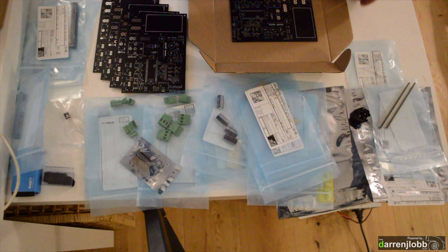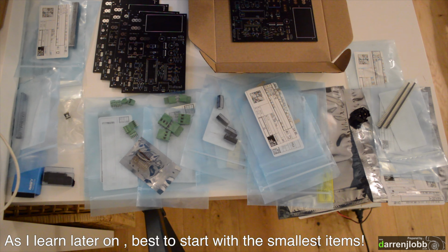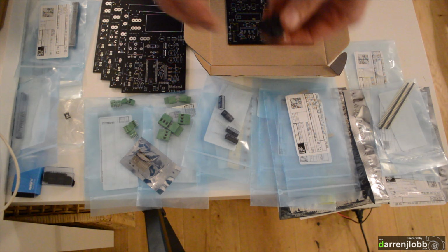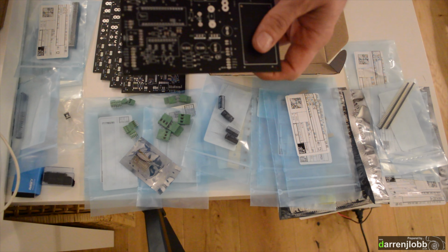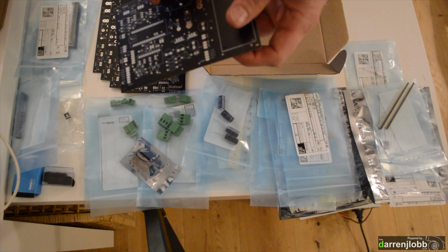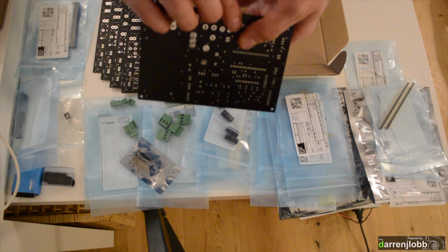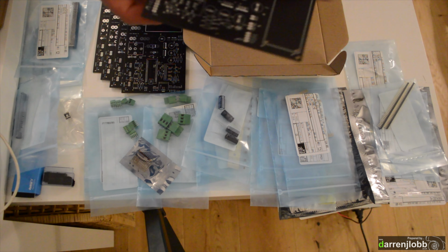So that's pretty much all the main bits and pieces you need to put this together. Really it's just a case of starting wherever you like and soldering them on one at a time. I think we'll start with something nice and simple, this relay holder, which is obviously going to sit on the board. You can't go wrong, it's going to go in the hole that's marked relay. Flip the board upside down, solder your 5 contacts and then move on to the next thing.